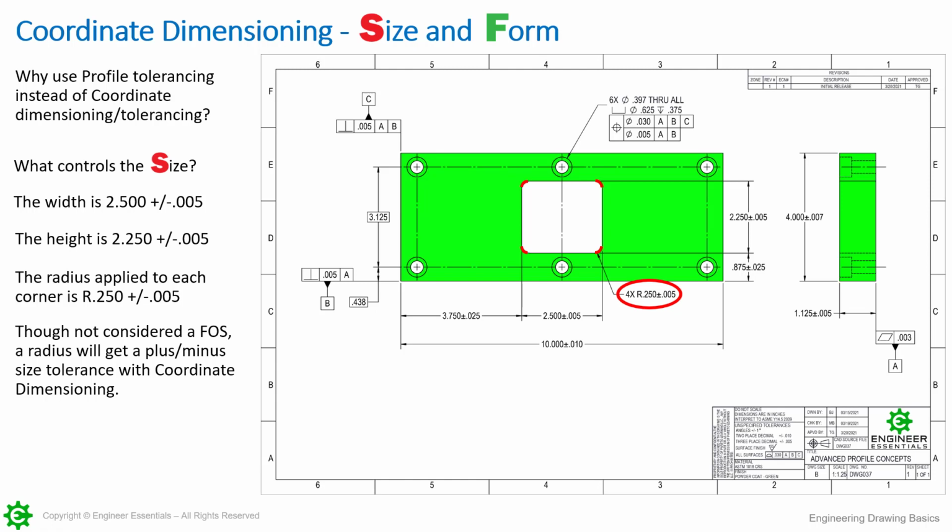The reason that I wanted to point that out, though, is when we get into converting over into GD&T, you see it very often, but we can't put a position tolerance on the radius. So that is forbidden according to ASME. Can't put position tolerances on those.